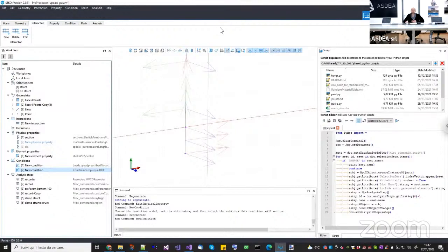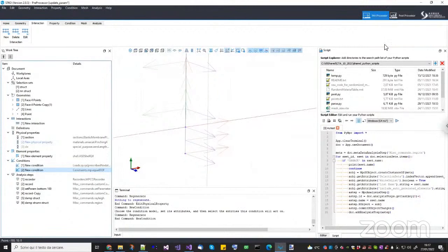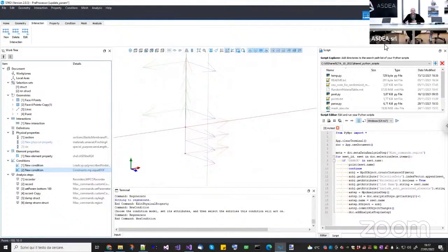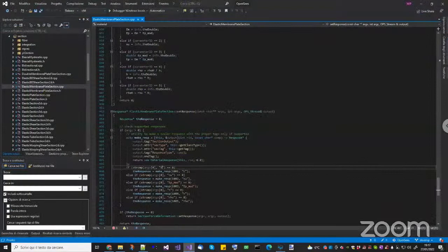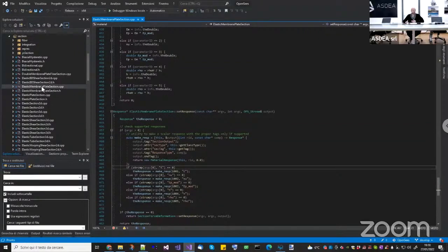Okay, so Aritra, can you share your webcam and your microphone, so we can talk about it? Because the second question is not completely clear. Hello, sir. I will first try to answer question number one. So you are saying that the zero length contact element does not record anything. Yes. Basically, after OpenSees 2.2.0, before that, we could record the things. But when OpenSees 3.3.0 came, when I'm giving the recorder for capturing the behavior, I'm not getting any behavior, for the zero length contact.